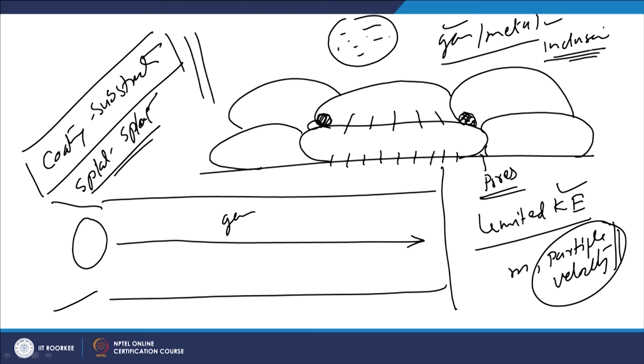So, the velocity of the powder particles is very crucial with regard to the high temperature exposure period, as well as the chances for interaction of the feedstock material with the gases which are present all around.